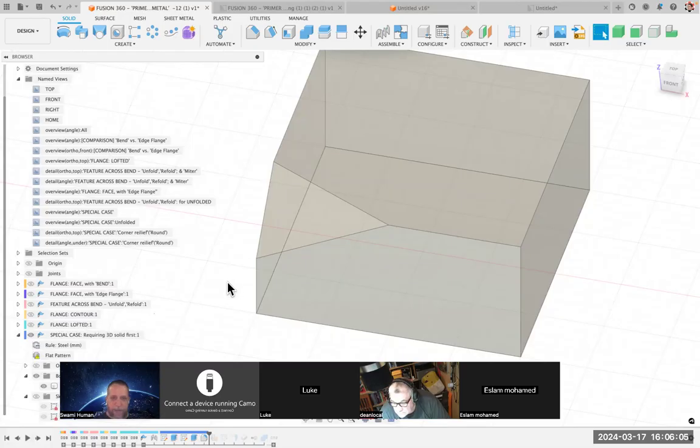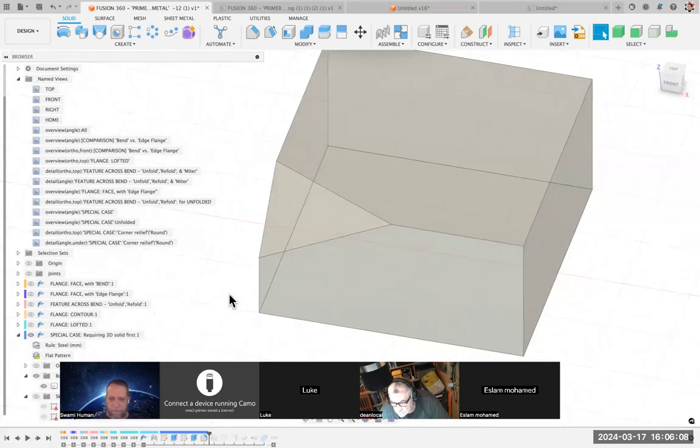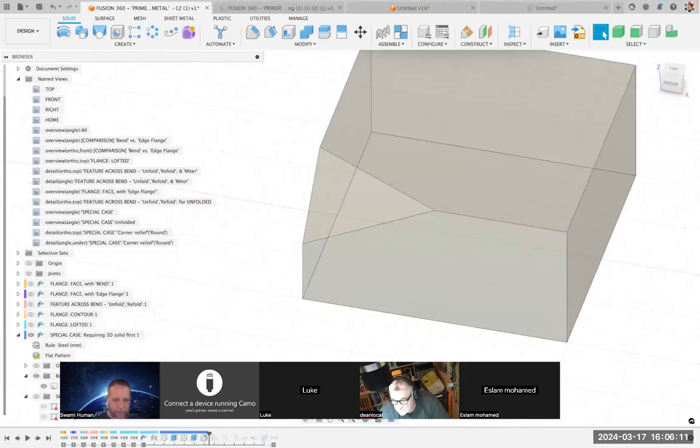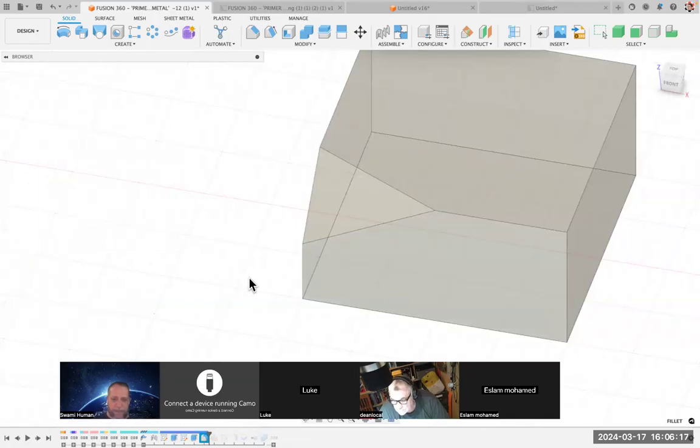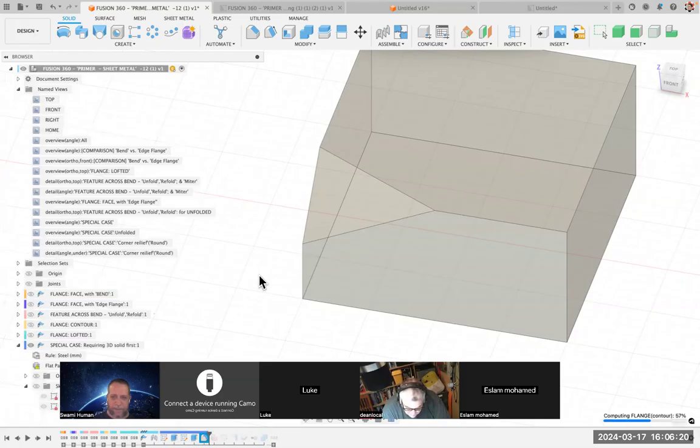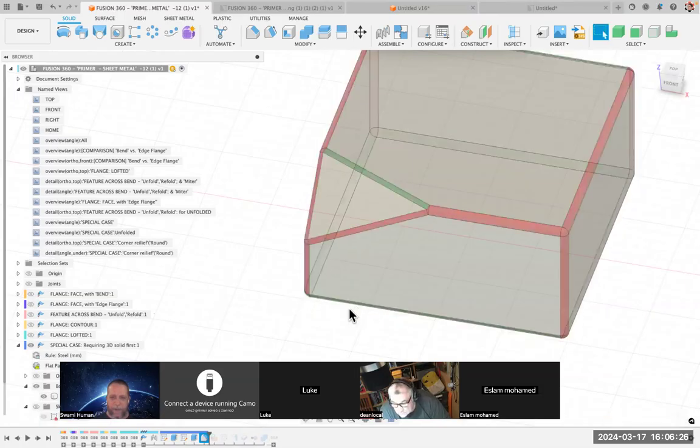Now I'm going to go ahead and make some things that aren't showing. Let me see if there's a problem with this. I'm making some fillets. I should see some fillets. Let me rebuild my timeline. They aren't getting computed. There we go. By the way, I hit Command or Control B, as in boy, for build, and that will recompute, recalculate the whole timeline. Something I did going back and forth, when I got to this point in time, did not properly compute that fillet feature.